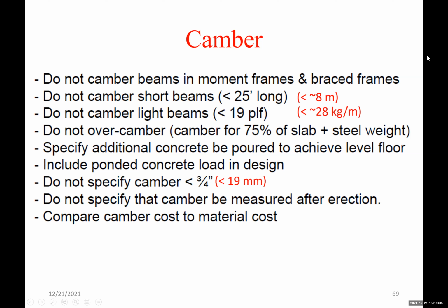Camber. Do not camber beams in moment frames and braced frames. In lateral systems, do not camber. Do not camber short beams, because camber costs money and could be expensive. So do not camber short beams that are less than 25 feet long.